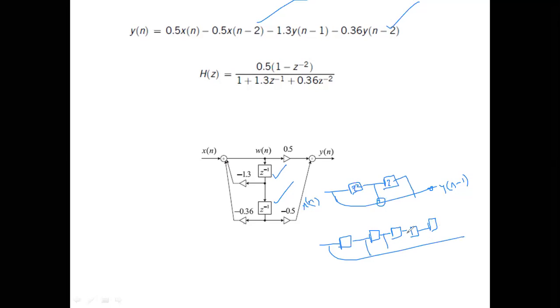So a higher order filter may be giving you a better frequency response, but its response is delayed. It is giving you a constant delay, which is very much higher. I will just concentrate on this. A second order filter results in an output which is delayed by 2 clock ticks, whereas a fifth order filter results in an output which is always delayed by 5 clock ticks.